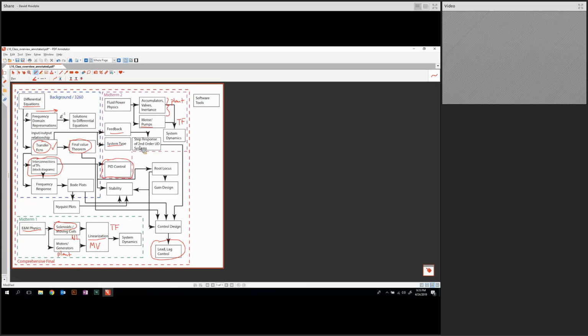We can also describe the system's response to a second order system. And so this we specifically looked at second order underdamped systems, but we said that, okay, most systems are more complicated than this, but we can use this kind of prototypical response of a second order underdamped system to try and understand more complicated systems. So even though it's not exactly second order underdamped, it could have extra poles, it could have extra zeros. Most systems behave approximately like a second order underdamped system.